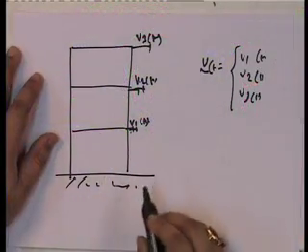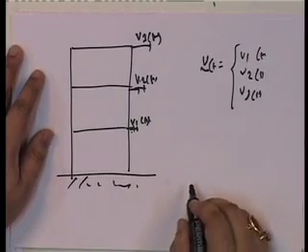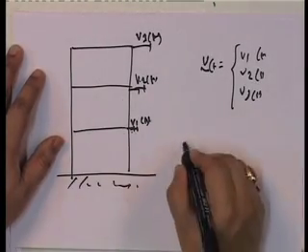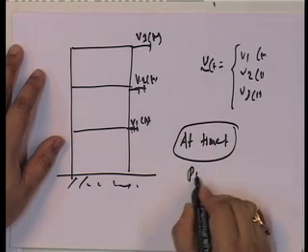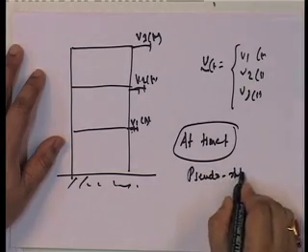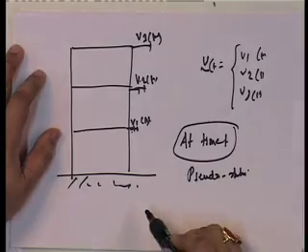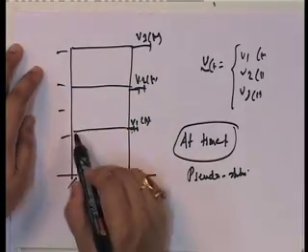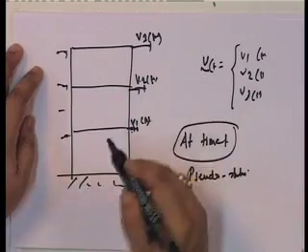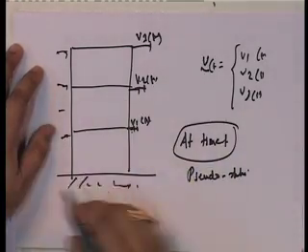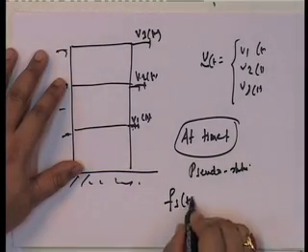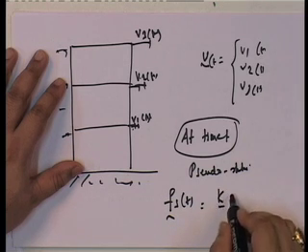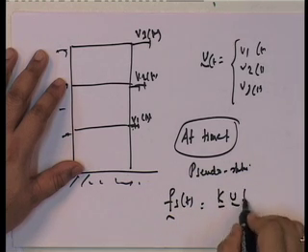Now, how do I find my base shear? Let us take the situation. Suppose it was a static load. So, this is pseudostatic at time t. It becomes a pseudostatic problem. To get this displacement, what are the forces that I have to apply? Static forces, pseudostatic obviously, which are going to give me these displacements? Well, we know that. What would be those forces? Those would be k into v, isn't it?